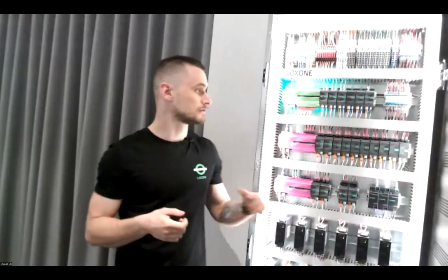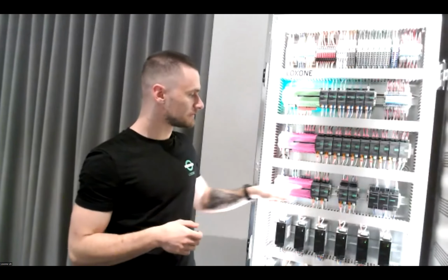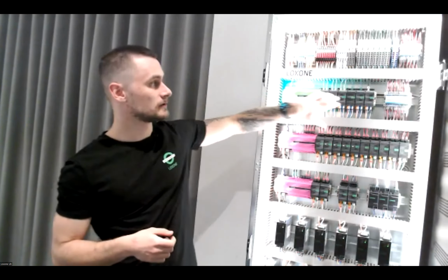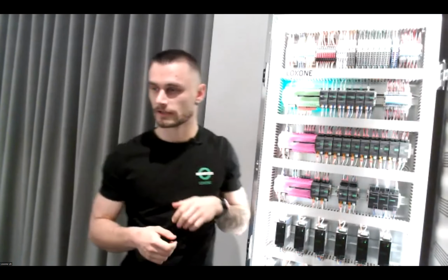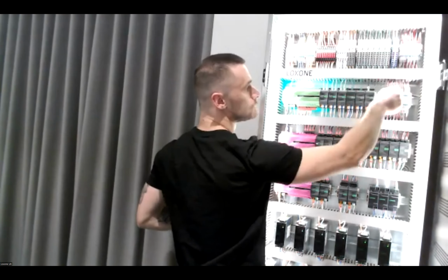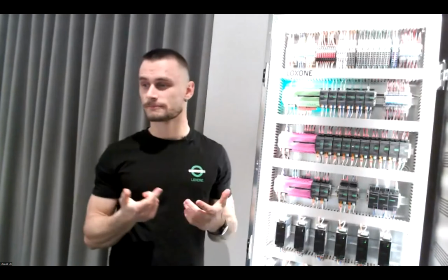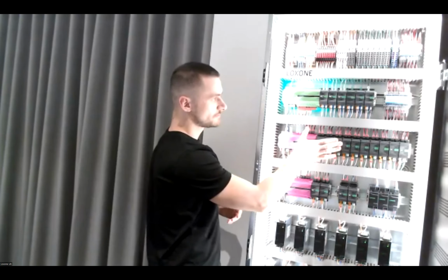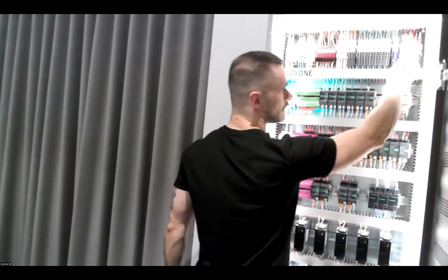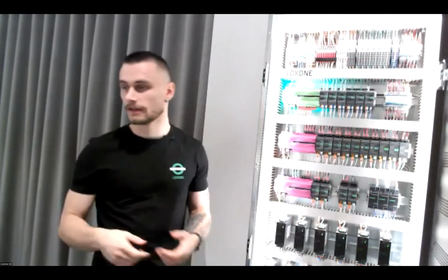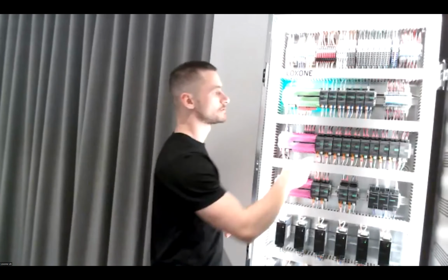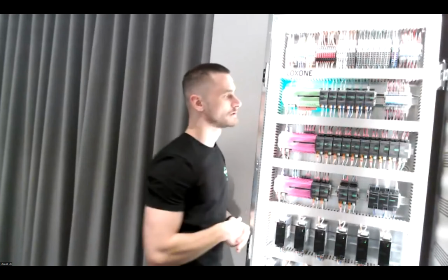for us, instead of going with the audio server on the second and third row, I'll actually have it higher up, because that way we can remove, oh, that's very bright. We can remove the terminals, saving money, saving space. And also, if you have the audio server higher and the stereo extensions higher, you can route them directly out of the panel, and then shorter distance plus easier for you to cable because you don't have all the cables coming from one place and one direction.